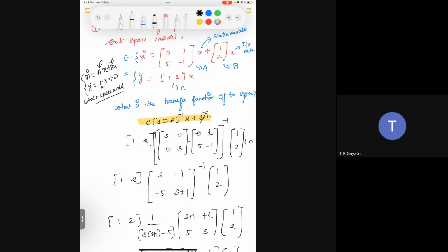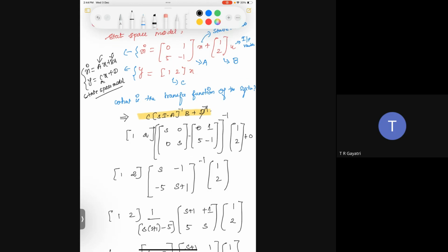So we have all this information. This is a general representation to transfer from one model representation to another. One is from state space to transfer function. If you want to go from transfer function to state space, then again you have to use Laplace, differential equations, Laplace and inverse Laplace. For converting state space to transfer function, this is a shorthand notation. It is given in the presentation. While doing content revisit, we saw this. Is it clear?